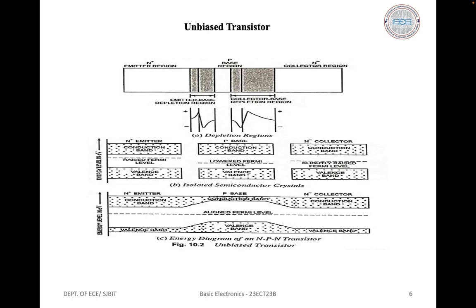Some of the charge carriers entering the base from the emitter do not reach the collector but flow out through the base connection. This can be seen here, but the path from the base emitter junction to the collector base junction depletion region is much shorter than that to the base terminal. So only a very small percentage of the total charge carriers flow out of the base terminal, and because the base region is very lightly doped, there are few holes in the base to recombine with electrons from the emitter. The result is that about 98% of the charge carriers from the emitter are drawn across the collector base junction to flow through the collector terminal and the voltage sources back to the emitter.